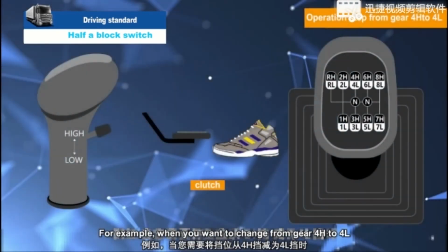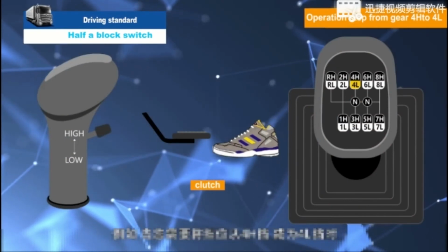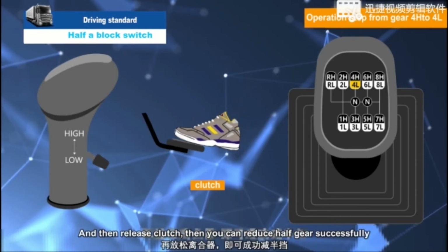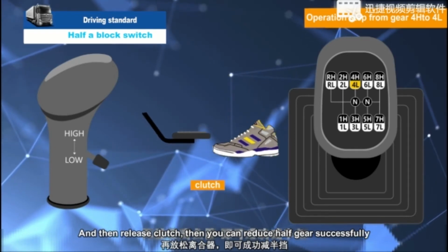For example, when you want to change from gear 4H to 4L, move the pre-selection valve downward and step on the clutch, and then release the clutch. Then you can reduce half gear successfully.